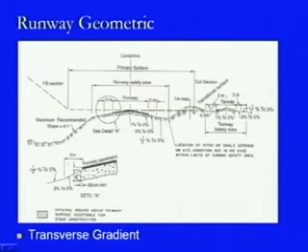So, we have 3 meters and 3 meters on the two sides, and then this is the overall safety area being provided, with a 4.5 meter distance on this side and 4.5 meter distance on this side. In this 4.5 meter distance area, the slope remains 1.5 to 3%.